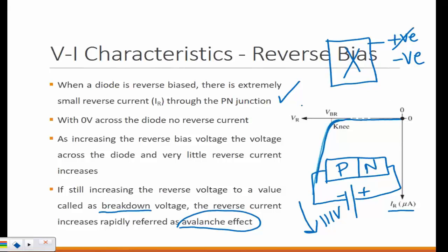But what is usually done is, we put a diode inside this device. So what will happen if you apply negative voltage? What will happen to the diode? It will be reverse biased and it will stop the source. Correct? So diodes can be used as protection devices too, for such types of applications.